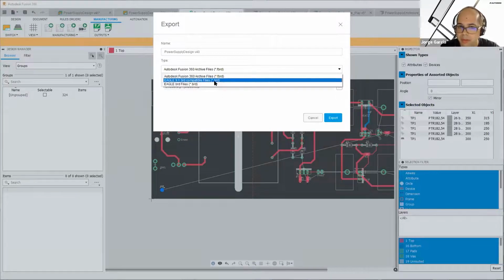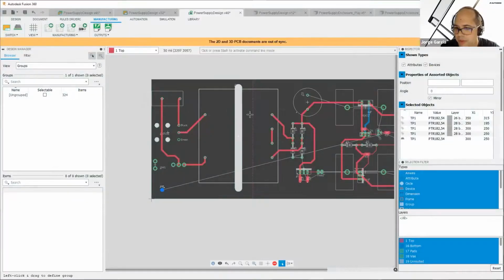One thing to keep in mind, very small caveat here. The polygon implementation in Fusion is much more efficient than the one in Eagle. So you don't have the trade-off of width to Gerber data size. In Eagle, it would draw the polygons all lines in parallel, and the width of those lines would basically determine how many it would take to fill the poly.